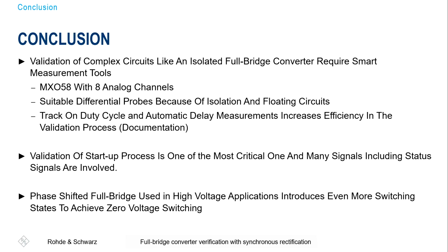And last but not least, this full bridge converter design was a hard switching type, so relatively simple, because the extended version of this hard switching full bridge type is the phase shifted full bridge, to have a resonance converter or bring it into a resonance case, so that you really have high efficiency with high voltages. And then you have many more states you have to validate. And this is even more complex, and that's why I think this full bridge hard switching type is only an intermediate condition.